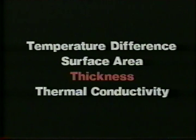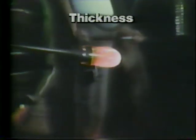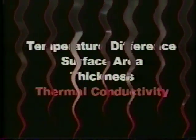The next factor in heat flow is the thickness of the material. Since heat energy can flow through solid objects, the thickness determines how far the heat has to travel. So the heat will move more quickly through a thin material rather than the thicker part of the same material. In glass manufacturing, the cooling rate is often critical to the final product. If molten glass cools too quickly, it cracks or shatters.